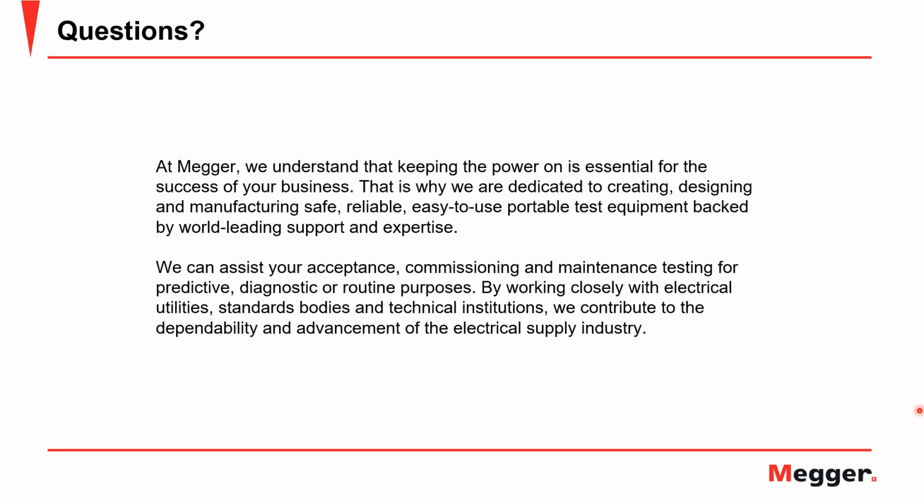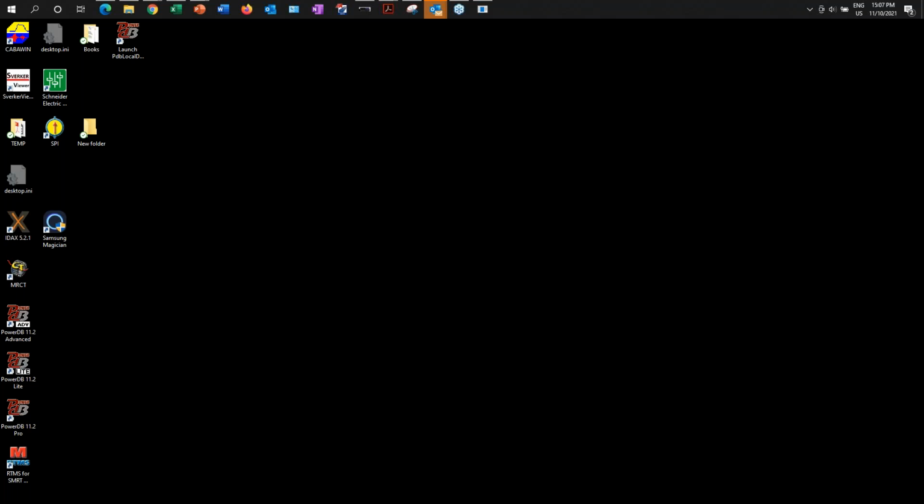Okay. When Abel was going through the summary, he did mention that directional protection can be used for supervision. So what it means is that, for example, you could use a directional element to supervise the distance protection, because the directional element adds additional security to your distance protection.